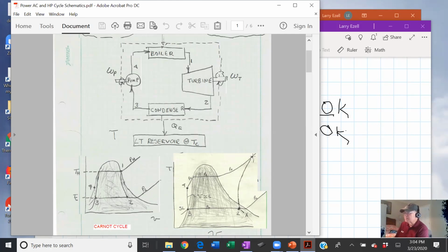So this is a constant pressure here, and let's say some typical values. Let's say 2,000 psi. Let's say 3,000 psi. That's on the high limit. That would be about 200 bar. You know, a bar is 14.5 psi or thereabouts. I just use 15 to round it. So I say in my mind, a bar is 15 psi. So 3,000 psi divided by 15, that's 200 bar or 20 megapascals. That's a very high pressure, about as high as you get.